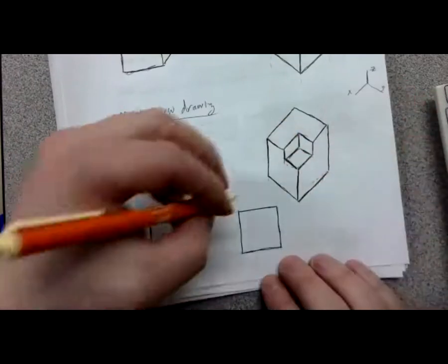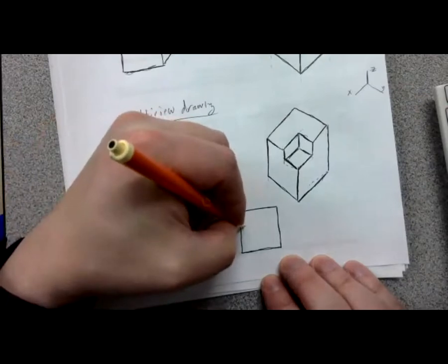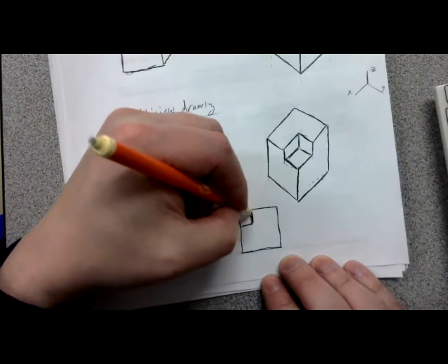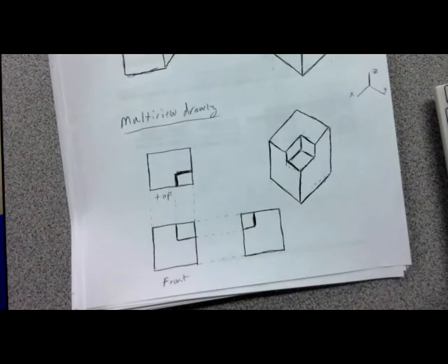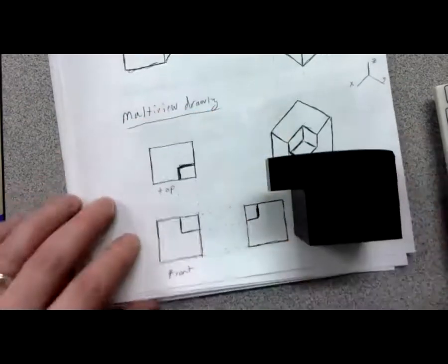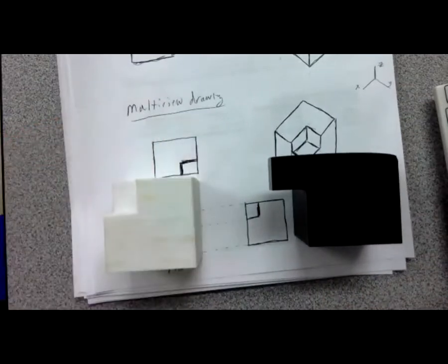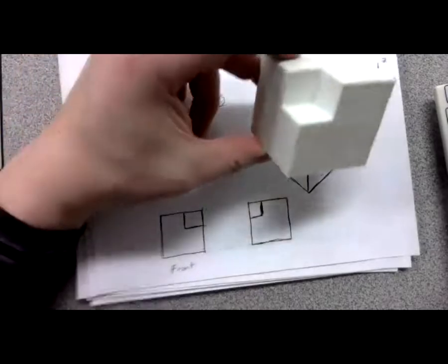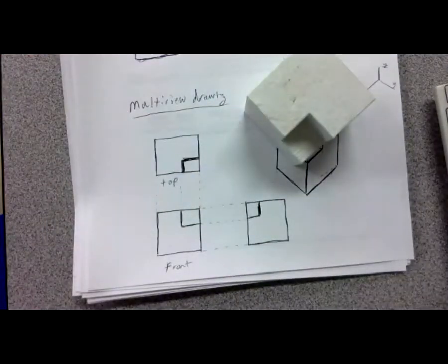You see it from this direction. And then if I extend this out, I can see how deep this should be. I will see in the top left-hand corner of the right view a little square there. Again, if it were this, this would protrude out. It's not. It's this. So it has this cavity there. The three projections work together to define the whole object. Questions here so far?